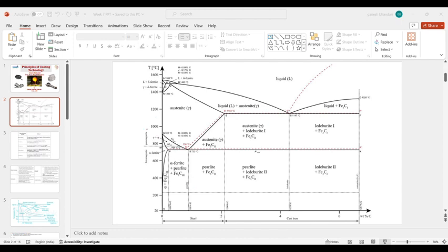Okay, so generally, after bainite formation through this heat treatment process and holding, we go with the normalizing process. Because if we go with quenching, it will create unnecessary thermal shock in our sample, and then we have to go with tempering, providing one more extra heat treatment process. And if we go with furnace cooling, then we are giving sufficient time for a bigger grain size, so that will also affect your properties. So generally we go with the normalizing process.